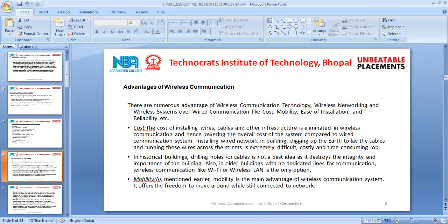Now, the next limitation is the spectrum limitation. As we know that India is a developing country, and we have very limited sources of spectrum. The spectrum available for wireless communication services is limited and regulated by international agreements. For this reason, the spectrum has to be used in a highly efficient manner. Two approaches are used. We have regulated spectrum usage, where a single network operator has control over the usage of the spectrum, and unregulated spectrum, where each user can transmit without additional control as long as he complies with certain restrictions on the emission power and bandwidth.